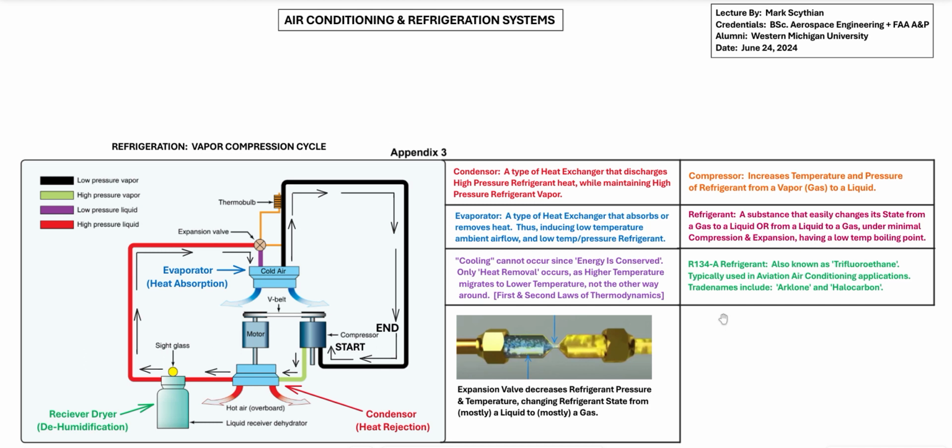So we are inducing liquefaction while inducing a boil at a relatively low temperature from the ambient atmospheric temperature, so minus 130. And initially, a long time ago, when the vapor compression cycle was experimented upon before air conditioning was commercialized, solvents or actually combustible gases were the primary choice, such as propane. And we see that when we compress gaseous propane, it liquefies at a very cold temperature, about minus 40 or below, but upon reaching a temperature above minus 40 below 0 Fahrenheit, it will then vaporize into a gas.